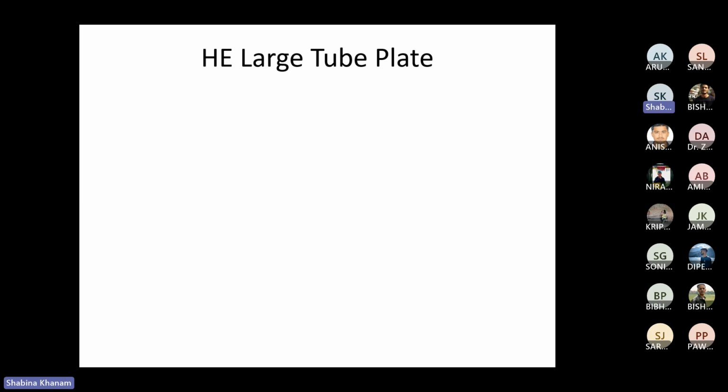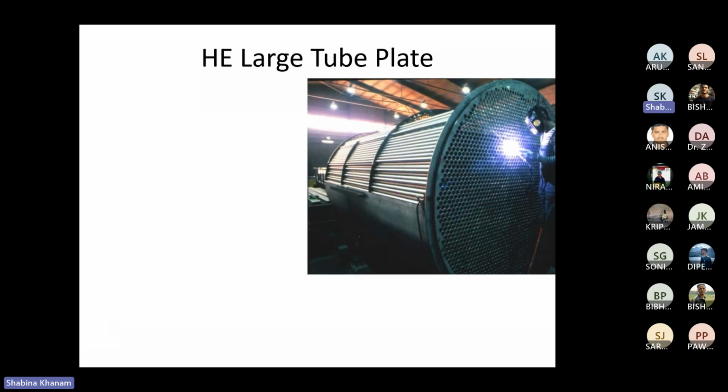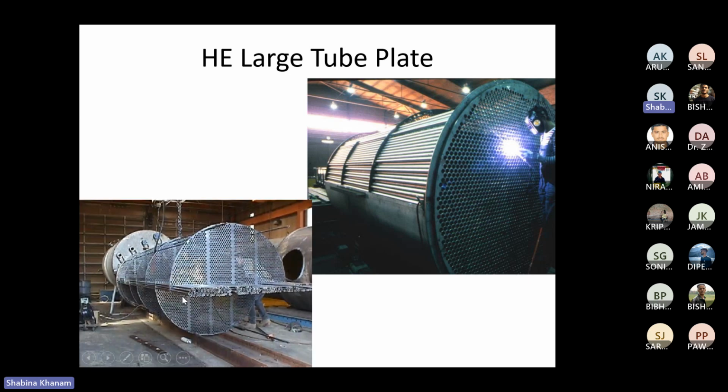Now I will show some images of heat exchangers which are very large in size. As you can see, the tube plate, that is this tube sheet, is very large. So this type of heat exchangers you can consider. And if you see, this is nothing but the baffles. These are the actual baffles, and the number of tubes you can insert in between these holes. So you can see the pattern over here. This is the triangular pitch pattern. In that way you can visualize the heat exchangers, which are quite large in size.